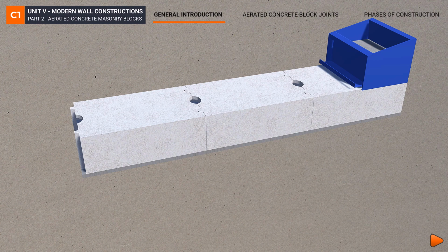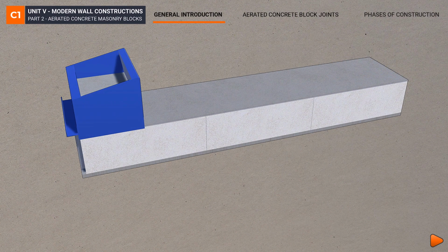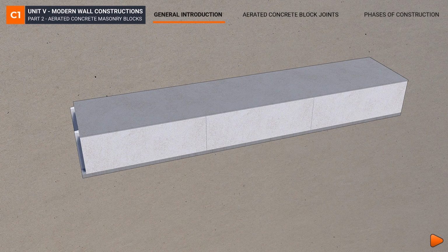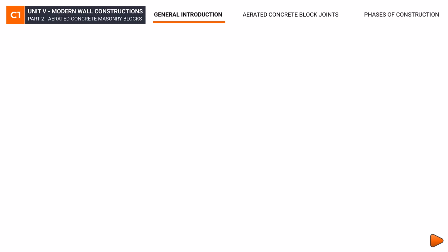This results in joints only 2 millimeters thick, which is both material saving and significantly reduces the amount of thermal bridging. Particular attention must be paid to precisely adjusting the level of the first course, similar to thin bed mortar solutions for clay blocks.